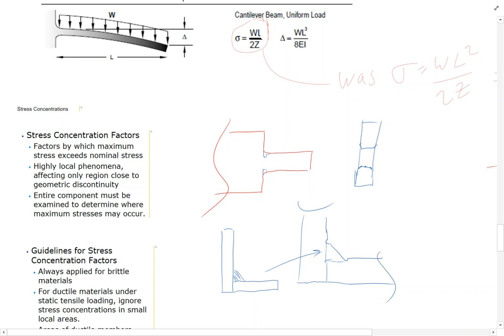If I'm on a manual lathe, is that easy to do? It's really not, because I probably can't turn this shaft with a really large radius tool like that. It just generates too much force, too much pressure. I'll get chatter, I won't get dimensional stability. So, you know what I'm going to do? I know this thing fits into this. In fact, I'm making this whole thing. So I'm going to go ahead and just put a little undercut in there. It won't hurt anything, right? Thinks the manufacturing person. But in reality, it does. It creates a sharp corner. That would be a point of fatigue failure. It would initiate, right?